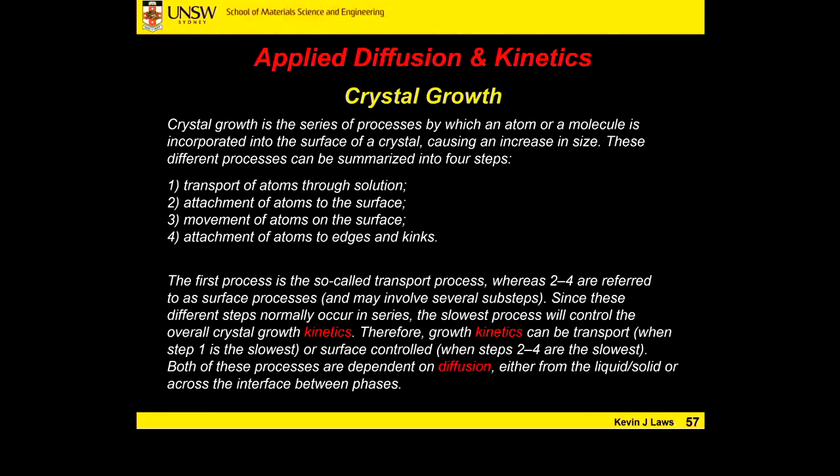Okay, so we think about a crystal, right? What's a crystal? Let's just think of a really basic cubic crystal lattice. Right? When you have a crystal lattice and a spherical embryo, because it's essentially squares, think of 1980s video games and things like that. It's all heavily pixelated. To make something that's round, it's still going to have steps on the edge, yeah? It's the same with a crystal, right? So we might have a spherical embryo, but of course, at the very, very surface there, it's going to be stepped. Okay? So steps in the surface provide sites of slightly lower energy for atoms to actually attach.